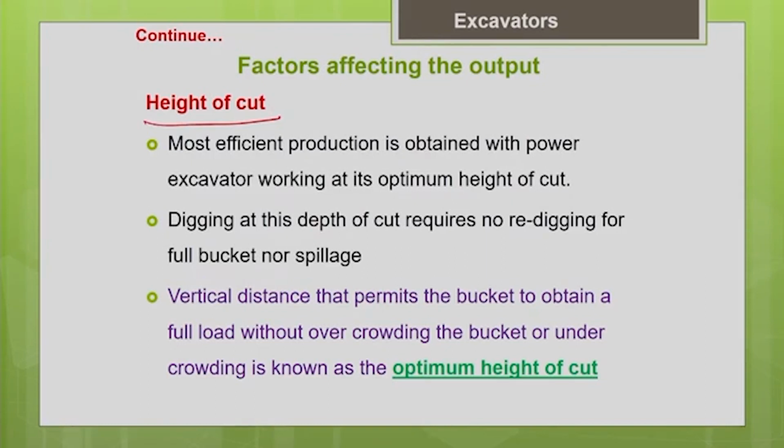Every shovel can give its maximum or optimum productivity at a particular height of cut of material. So the machine will give you optimum productivity only at the optimum height of cut. That optimum height of cut for a particular machine depends upon the dimensions of your machine.